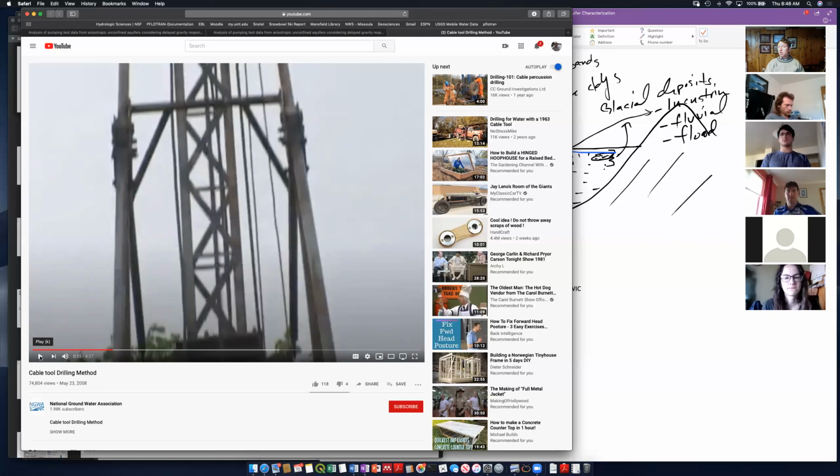And that'll let us know what kinds of drilling techniques we need to use. So as an example, we don't need to go very deep and we're in unconsolidated sediment. So wireline could be a potential possibility here for us. We'll talk a bit more about application, but one of the important things to think about is where we can do these types of methods.